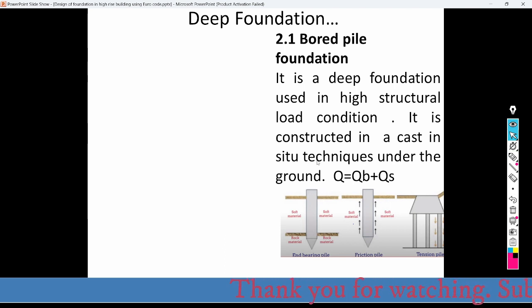If the majority parts of the columnar load coming from the superstructure is resisted by the end bearing parts of the pile, so the pile will be called end bearing pile. And here we have also the tension pile. Here the direction of friction is in upward direction in the case of friction pile, and the direction of friction or force will be down in the case of tension pile.